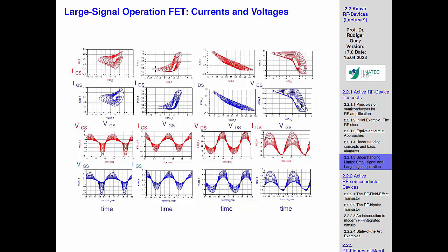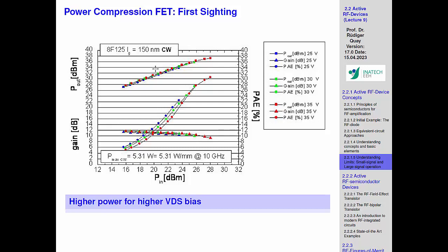And you see, this is why we are doing this. You also see that for low power values, you see a perfect sine wave. But when you start to compress, this sine wave is also modified. So you see compression not only from coming down in power, but what we call saturation here. The power is not going up linearly anymore with the input power.